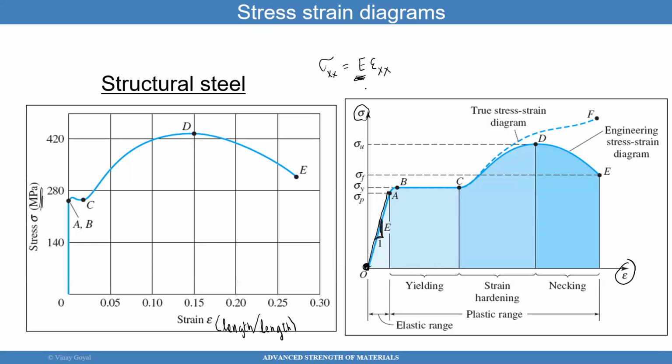You typically, at least in aerospace designs, want to try to design so you stay below the yield point. You want to stay in that zone linearly. You can't go above yield, but then you have to look at the potential effects of fatigue; form, fit, or function could be affected. You want to make sure that there are no other potential failure scenarios of concern. So at least in aerospace design, we try to design so we're staying below yield.